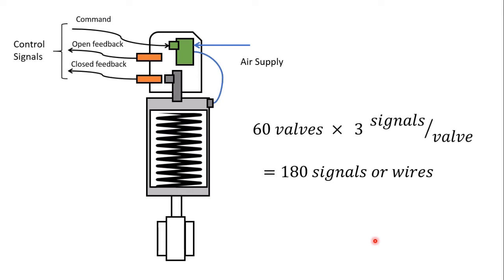to be installed and wired to our PLC for our example plant. So you may think that 180 wires is a small number, but 20 tanks is a small number for some plants out there. Secondly, PLCs are usually installed in a room or an MCC which is far away from the valves themselves, and the distance becomes more than 100 meters in most cases. Now running 180 wires over 100 meters is not a joke. Remember that cables in a plant do not run in straight lines. You need to climb up to the ceiling, run it across to the equipment, and then run it down again.